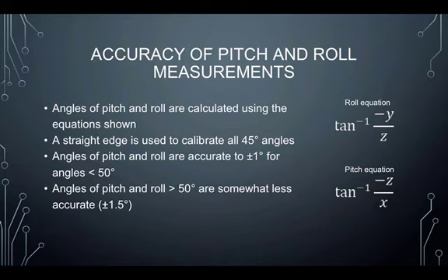This is due to the sine-like nature of inaccuracy produced by the accelerometer itself, which inherently introduces a plus or minus 1.5 degree inaccuracy. This inaccuracy, compounded with the rounding of integer numbers for displaying, results in an inaccuracy of about 4 to 5 degrees in the max extreme angles.